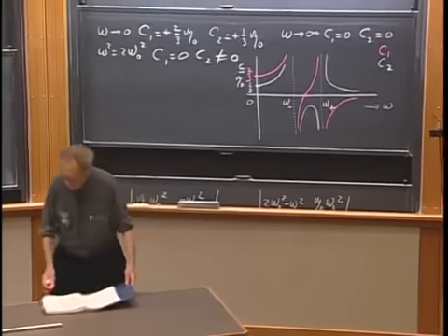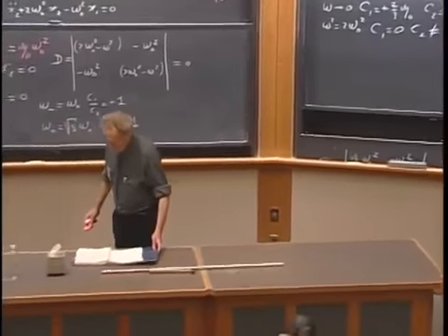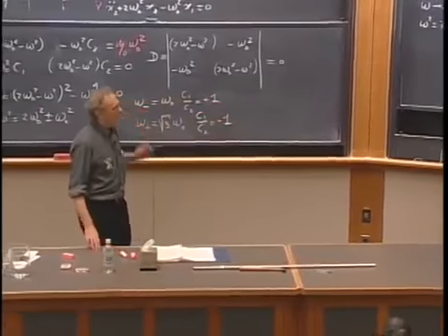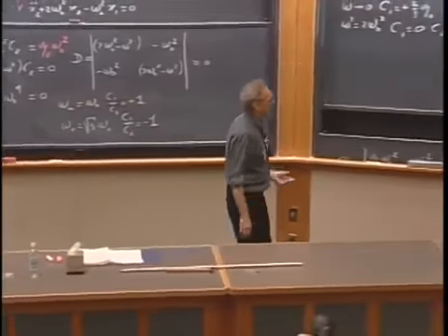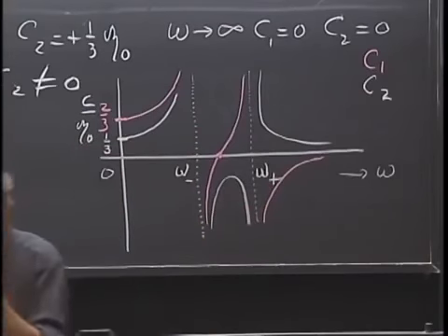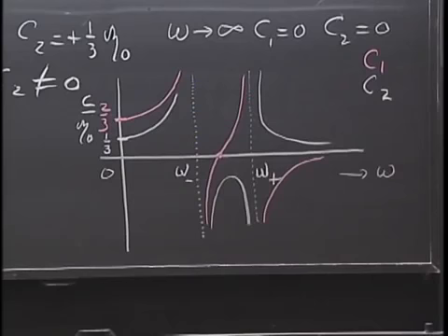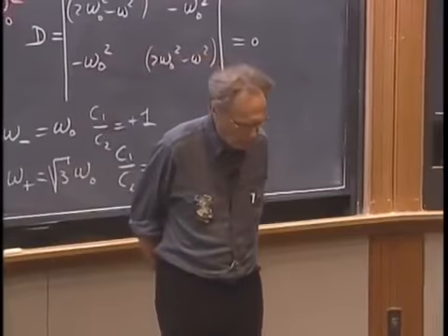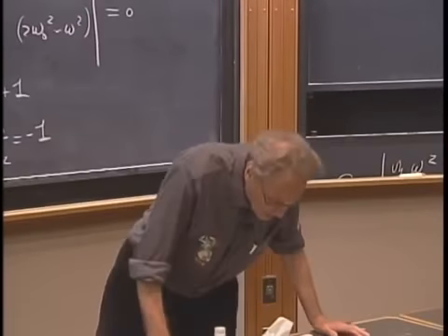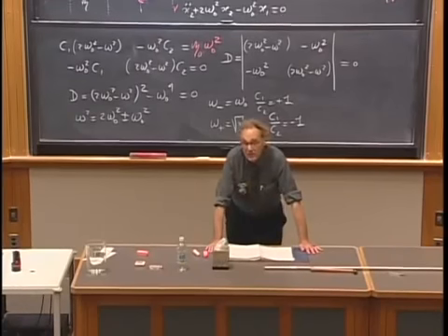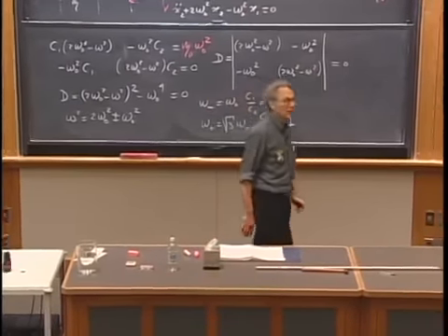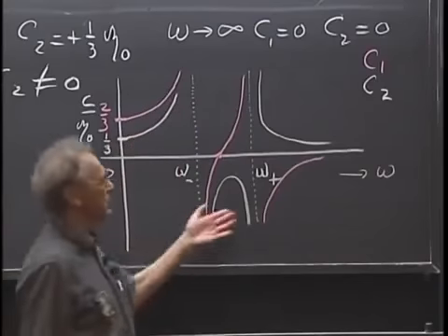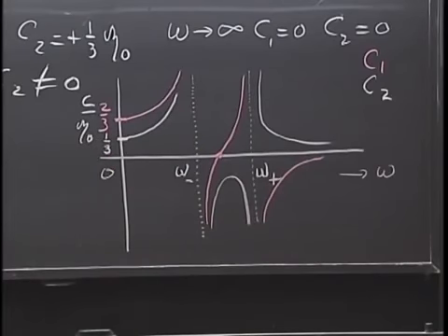Now we ignore damping, and because we ignore damping, we get these unphysical infinities when you hit the frequency omega minus and omega plus, these resonance frequencies. Now if you include damping, then the solutions become extremely complicated, but of course you avoid the infinity values, but the resonance amplitudes can still be very high. And so these plots are still very useful, provided that you don't interpret the infinities as being real, but something that is very large. If Q is high, then of course the amplitudes are enormously high. And this can lead to destruction.